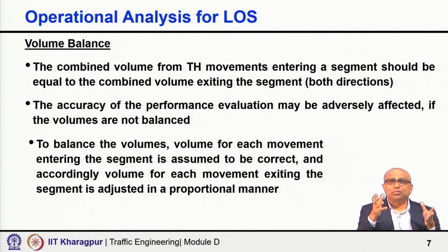So, the combined volume entering the segment must be equal to the combined volume exiting the segment, and that balance must be ensured for each direction. The accuracy of the performance evaluation may be adversely affected if the volumes are not balanced, because then the entering volume and exiting volume during the analysis period in the whole segment are not equal.